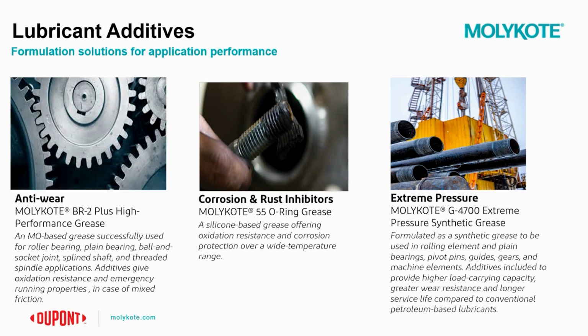It's a good standard O-ring lubrication grease that also offers excellent resistance to oxidation, robust thermal stability, and good corrosion protection. Additionally, if you have an application in an extreme pressure sort of condition, MOLYKOTE G4700 extreme pressure synthetic grease offers EP additives, extreme pressure additives, that provide higher load carrying capabilities and greater wear resistance, as well as longer service life compared to a lot of other conventional petroleum-based lubricants.